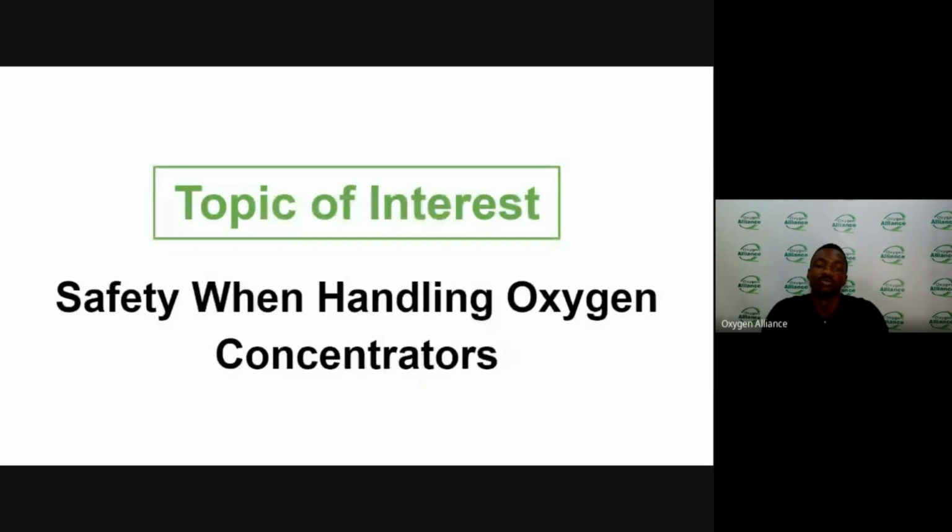Yeah, so that's true. So we always need to make sure that when we're working with these machines, all the wires are covered, because if the wires are exposed and then maybe someone is trying to clean the floor area, they might get some water on the bare wires, and that will cause a short circuit, which would either hurt the person that is cleaning or maybe even damage the machine. So always make sure that all the exposed wires are sealed.